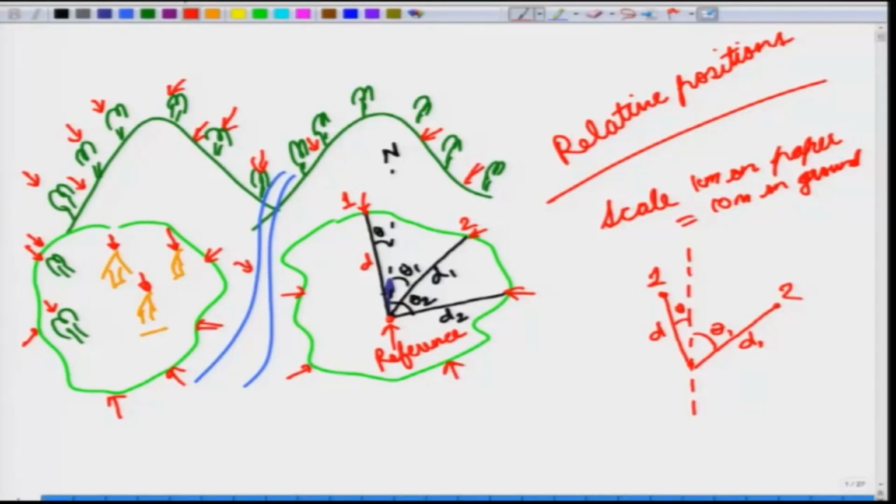Now, in certain conditions you can even go for 2 reference points. So, in this case you will say that this is my one reference point and I am drawing a straight line and this is my second reference point. So, when I have to take the measurements of the pasture, I am making use of the first reference point. When I have to take the measurements inside the village, when I have to have measurements of the houses or of the fields, then I will make use of the second reference point. But then both of these reference points are correlated to each other.